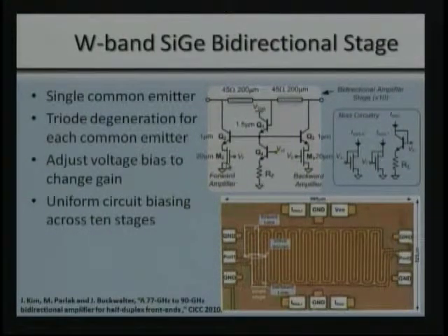And so we can turn on all the forward amplifiers by turning VF to a large value and turning VB down, or vice versa. So this is what this amplifier looked like. Basically, we use these serpentine transmission lines because it allows us to keep the path between the base of Q2 and the base of Q3 as close to the emitter of Q1 as possible. We want no delay through that signal path. But we want the transmission lines to be roughly 90 degrees at this frequency.